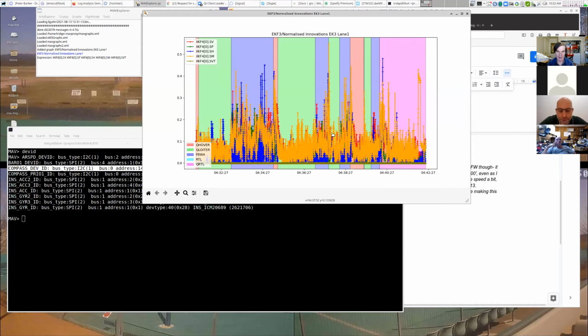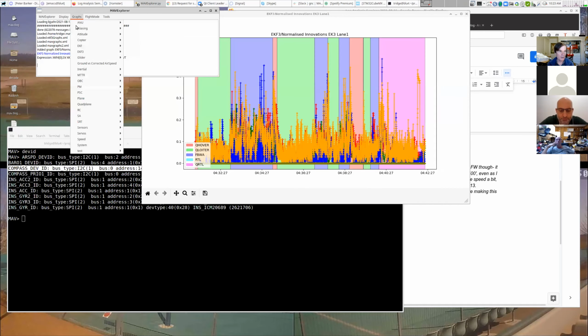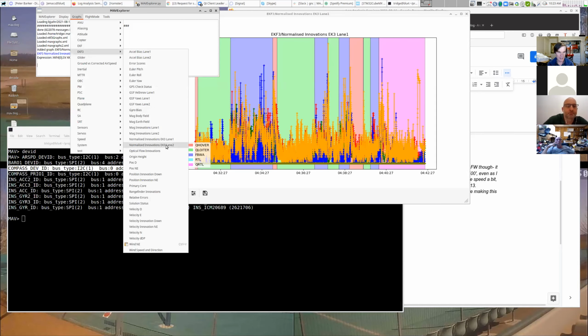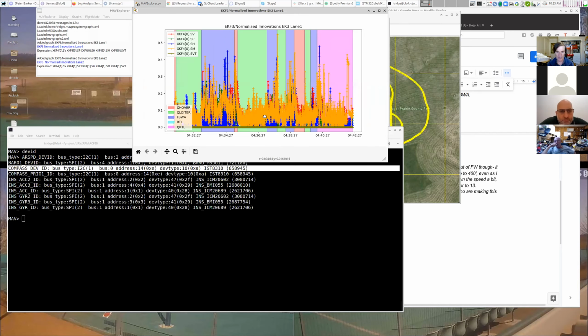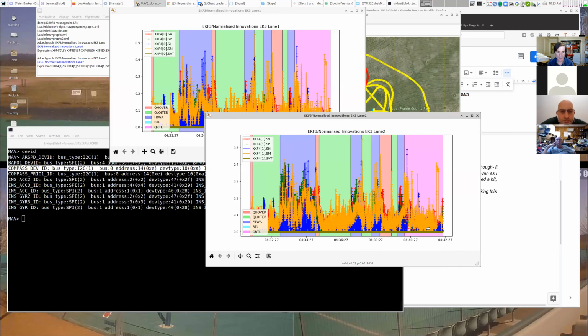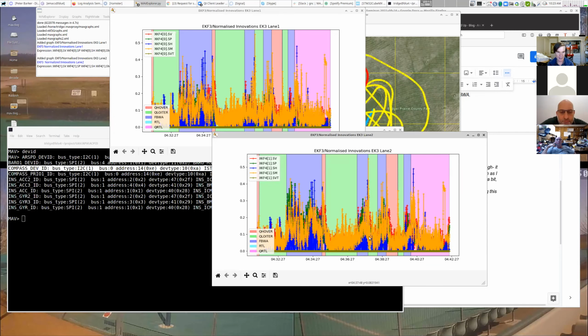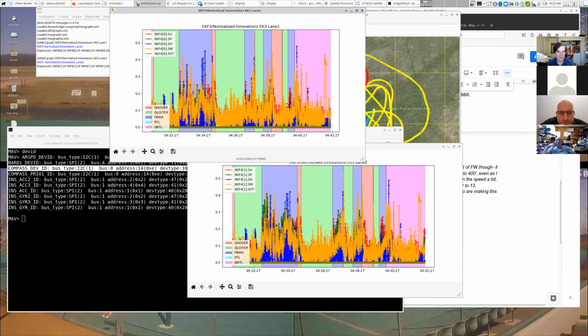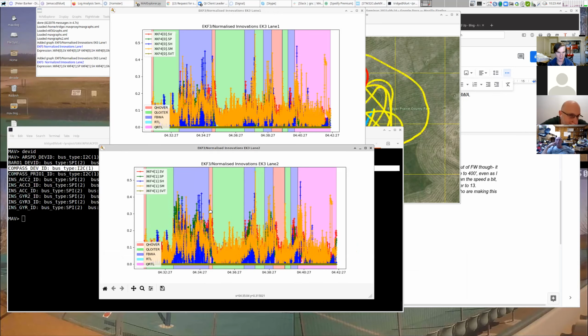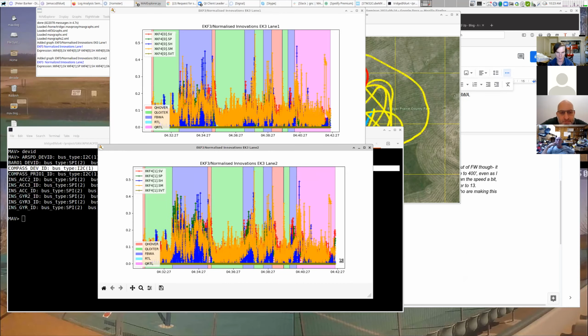Okay, so we can have a look at our first lane state estimation and our second lane state estimation. I particularly wanted to have a look at this state estimation because on my aircraft, I had noticed that the second lane tended to be a lot better state estimation than the first. Now on his, it isn't. On his, this first lane and the second lane are actually incredibly similar, right? So very, very similar.